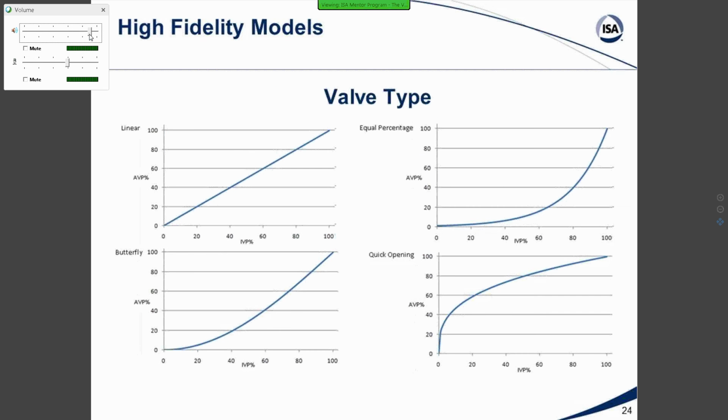So I mentioned that one of the things you might start improving is getting the correct valve characteristics. This may be anything from implementing the correct valve opening for a certain control system output, as this has a big change in where your plant is going to operate. If your operators know that it runs at 50%, you'll need the right valve characteristic in order to get the correct response.